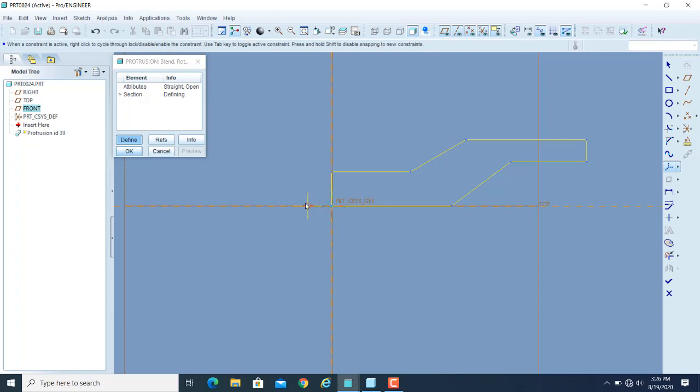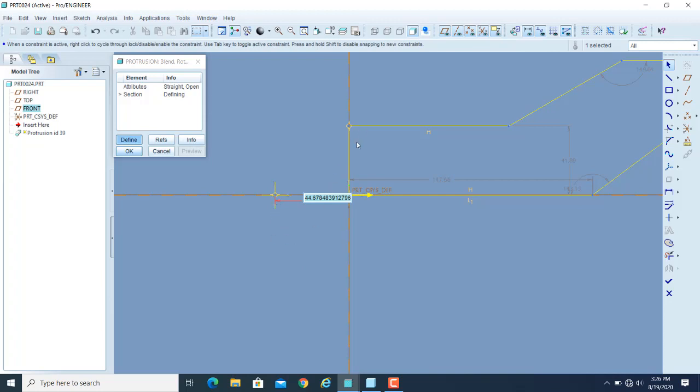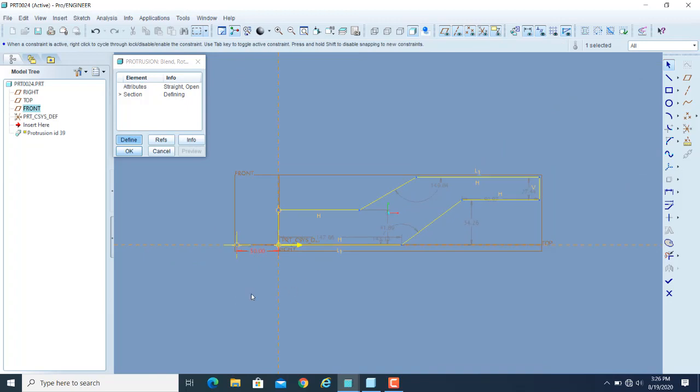And suppose let me give some offset distance of the axis from the original entity edge. So suppose I define it here. So once you define that, you can also set the offset distance in between your axis and the entity. So suppose it is, let us say, 50 units. So now we will have that 50 units of hollow space or hole, you can say, in that revolved object.